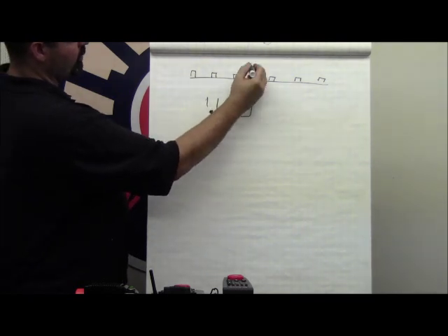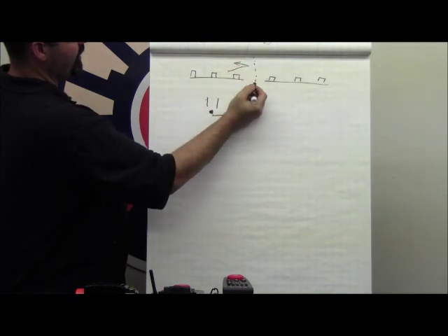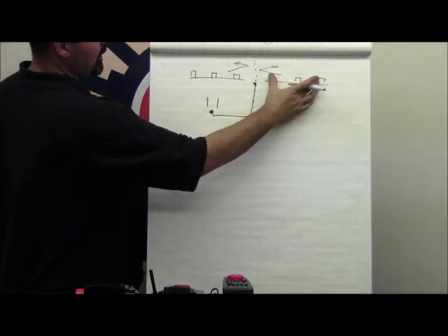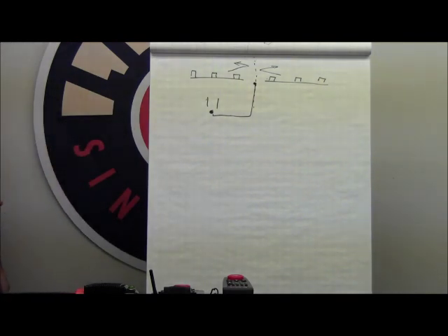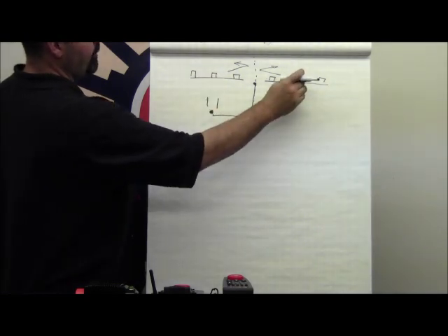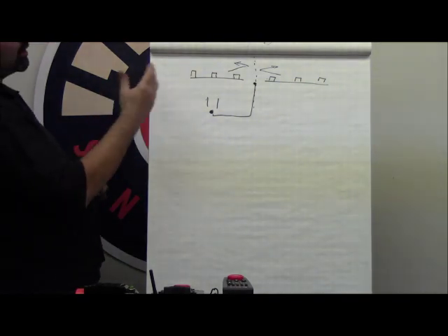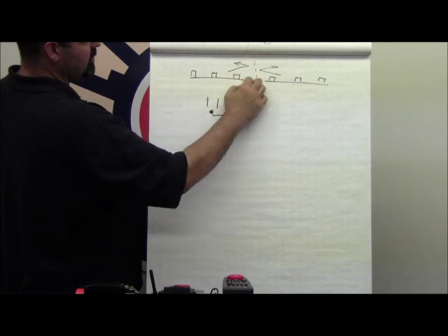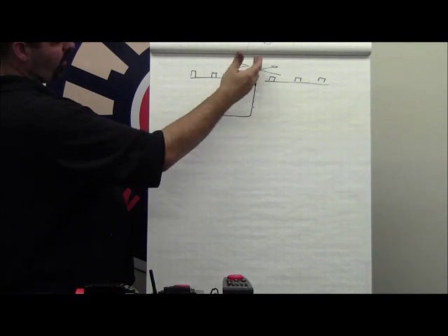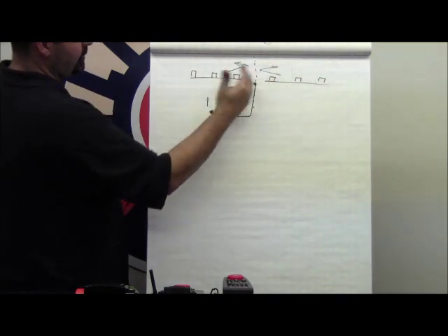With this in place, what we're doing is we're effectively making a force field that keeps this signal on this side and this signal on that side. Yes, both command signals are being broadcast from the same base, but depending upon the wire length of the bus feeding this track and the bus feeding this track, we can have literally a matter of a millisecond causing us to have 120 pulses of signal in this area. By having this ground plane installed, or this ground wire that's functioning as a ground plane vertically, we're separating the command signal on either side.